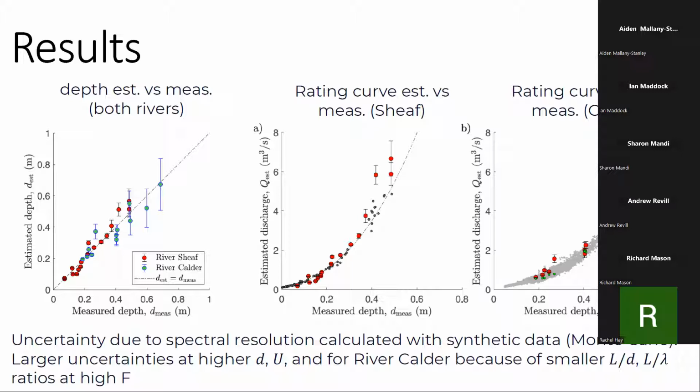So is it just the width though? My concern was that some of those features might be created by the walls of the channel because it's so narrow. Even if it was, it wouldn't matter. What causes the waves doesn't matter. It could be a bridge pier, it could be a drain, it could be someone paddling a boat or a boulder. It doesn't matter because waves would still follow that behavior. Unless there are conditions where maybe that would fail, and that is if the waves become very steep and then there are some nonlinearities. But there could also be ways to cope with that, even in that case. But in general, it doesn't matter if it's wind or what is causing the waves.